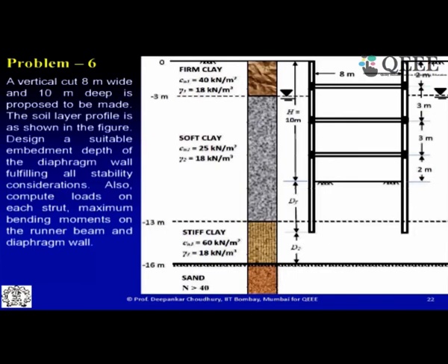other. So from the ground, the first strut is provided around 2 meter depth. Typically we generally provide about 1 to 2 meter depth. Within that, the first strut has to be provided so that maximum deflection at this portion near to the ground can be avoided. Then the second strut at 3 meter, another strut at 3 meter has been provided over here.